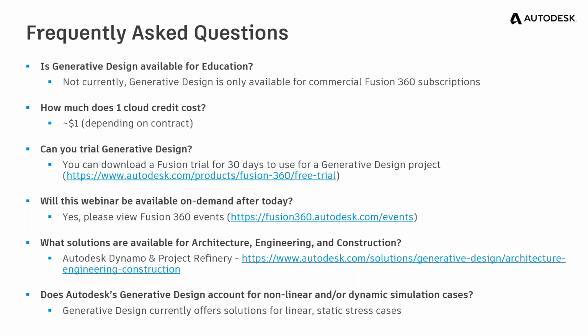Question here as well, is there any FEA report for the build models? So within generative design today, when you set up the load cases and you get that final outcome, it is not carrying any of the information as an FEA report itself. What it is giving you is the setup that you can go into either Fusion simulation package or now our partnership with ANSYS to then revalidate and get a full FEA report from that model.